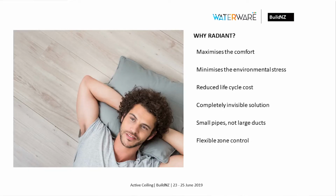And we also have reduced life cycle cost. Because the temperature which we're trying to maintain is so close to our target temperature, in heating, the water temperature we'll be sending is probably about 30 degrees. So there's about a 4 to 5 degree difference between the water temperature we send and the surface temperature that results. So in a ceiling-based system, we'll be sending 31, 32 degree water, and then the surface temperature on the panel will be maybe 26, and then the resulting temperature in the room will be about 21.